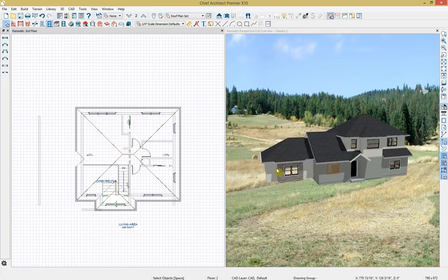The way automatic roofs function is that you use the wall to tell the roof plane above it how it's going to build. So if you're going to be adjusting the pitch, you do so from the wall to tell the roof plane bearing on it how it's going to adjust. So I'm going to select these two walls. I'm going to select them both at once by holding down my control key.